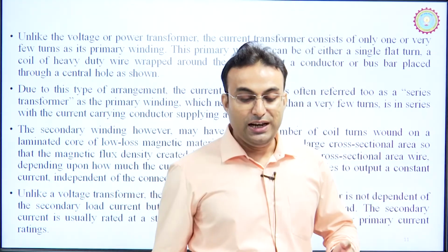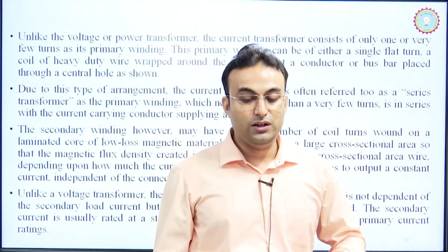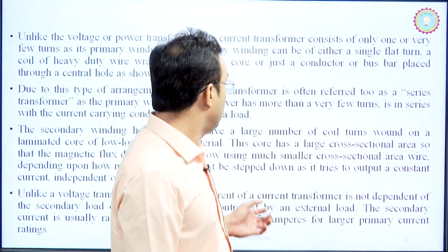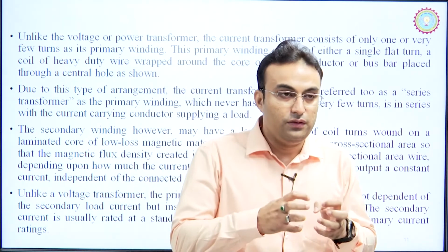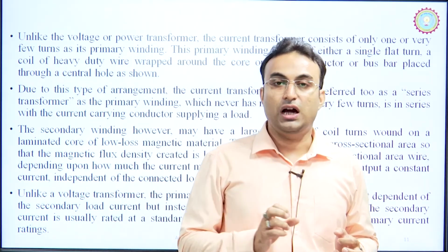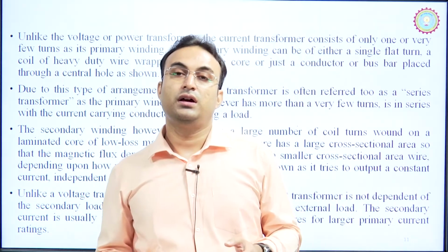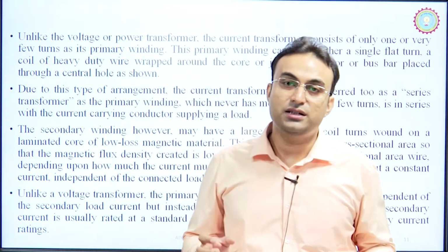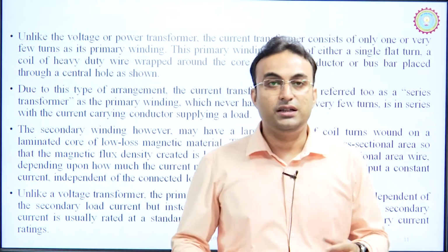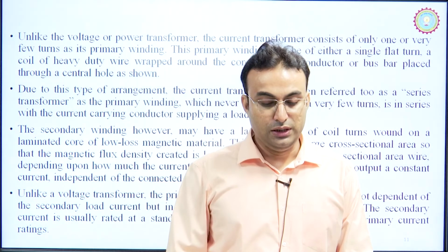Due to this type of arrangement, the current transformer is often referred to as a series type of transformer, because, as I told you, the current which we want to measure passes through the primary of the current transformer. That is why we call the current transformer a series transformer.